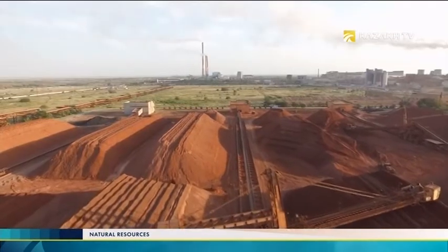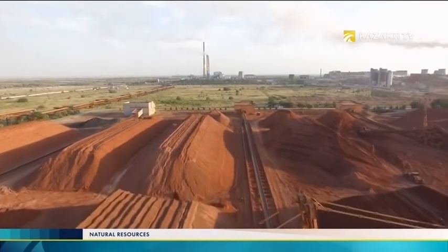The sintering unit is the first stage of ores blending. On the whole, the unit of raw materials preparation consists of 2 sections. The first section is designed to receive delivered raw materials to crush them in accordance with the predefined parameters. Bauxite is crushed into pieces of 100 millimeters each, coal and limestone 40 millimeters. The second section is used to put blended bauxite to the hydrometallurgical unit and sintering unit.